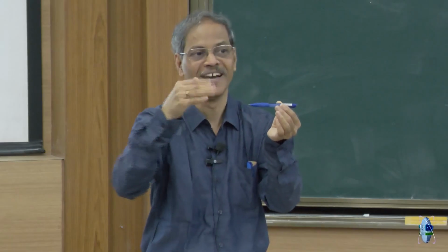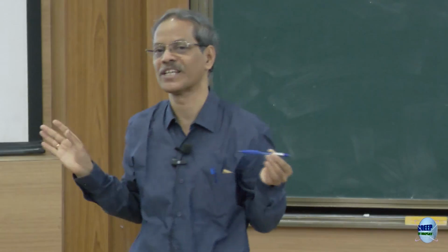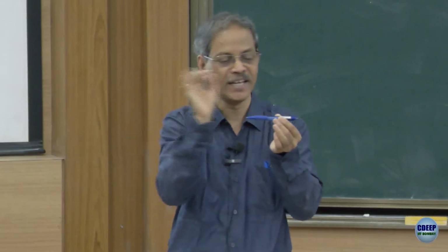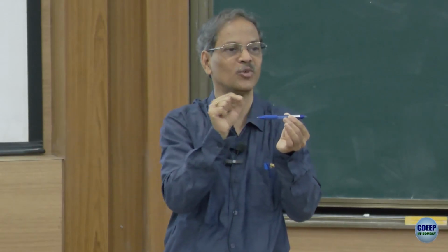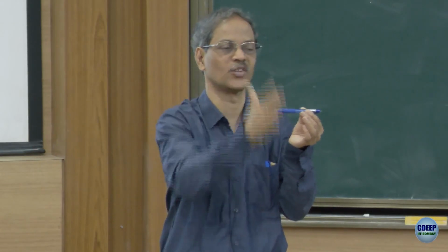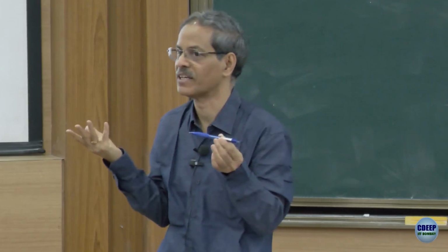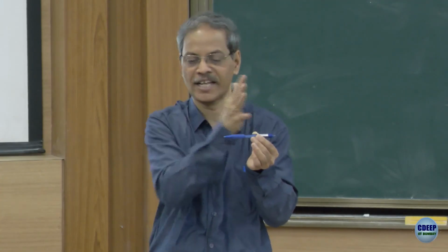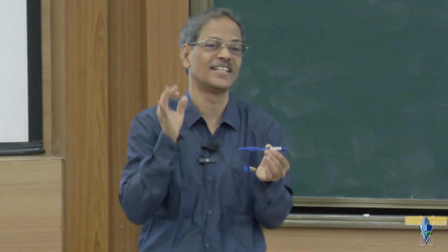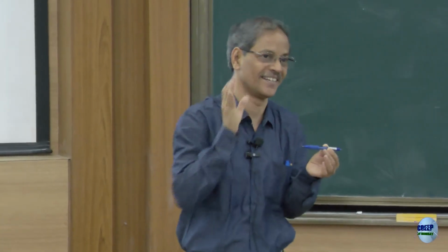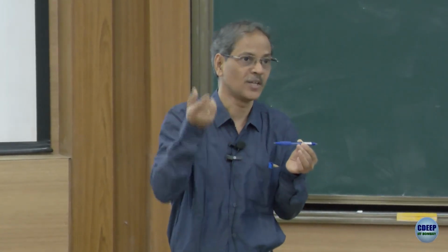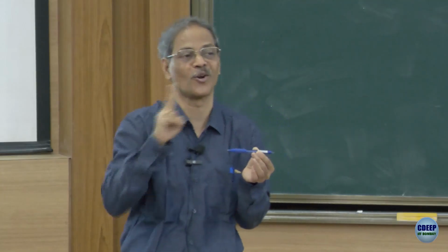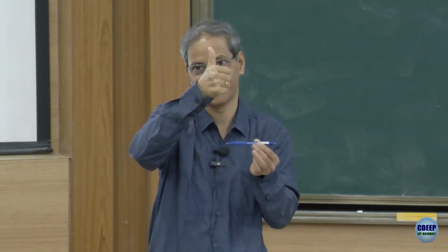So, therefore, I knocked out the entire cross section. I need to know only along the length how the deformation is changing, because the cross section is fixed for me. Immediately, the moment I know that this point has moved from here to there, I know that the entire cross section would have moved. That's a reasonable assumption I felt, I made it. That is how 2 dimensions were knocked off along y and along z.